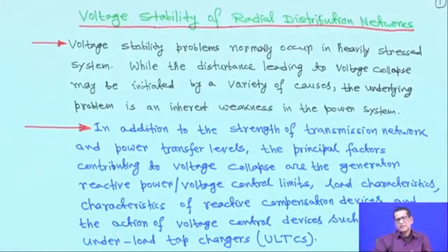We have not done it through the Newton-Raphson method, but the coupled Newton-Raphson method also works equally well. In that case computational efficiency may be less, but here we are exploiting the radiality of the network and developing the algorithm based on that. So, you should study well up to a 4 bus or 5 bus problem, and see how things can be solved.